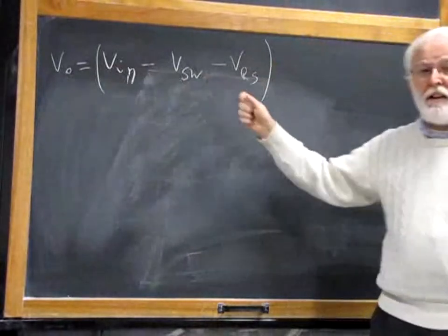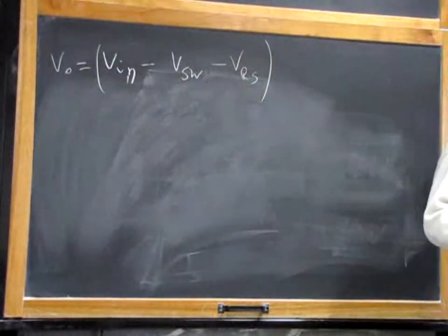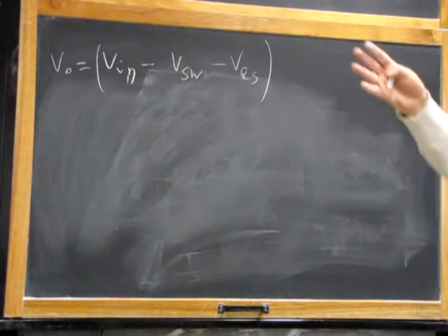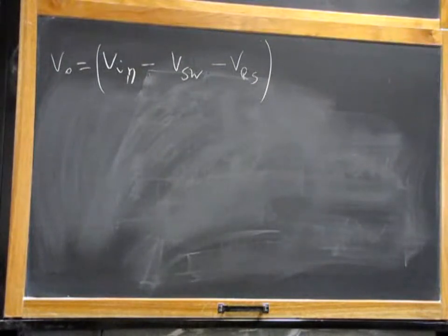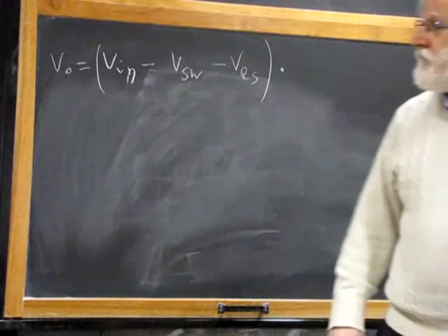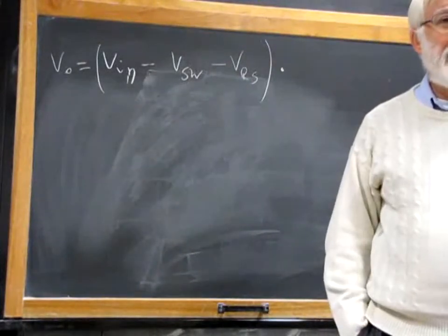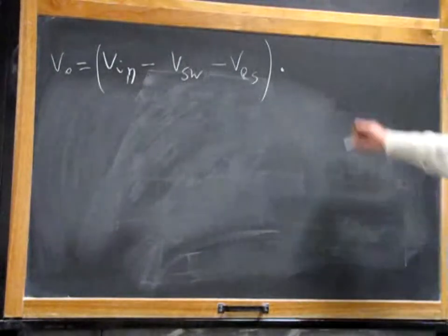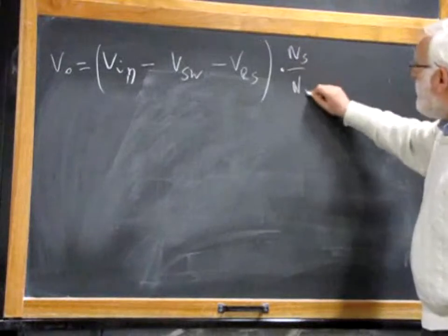What I forgot to put in this parenthesis, I forgot because I don't know how to evaluate it. The resistance of the wire. The wire resistance and the primary. That makes a voltage drop that reduces basically the effective voltage that is applied to the ideal primary winding. This voltage is transferred to the output side via the turn ratio, and the turn ratio is NS over NP.